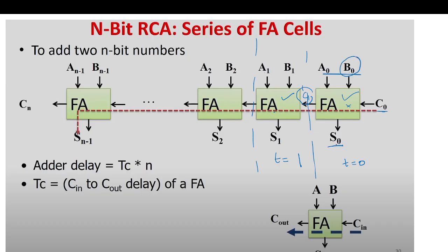So this data we wanted to come serially, like B0, after one cycle B1, after one cycle B2. So we needed two shift registers for this, and we needed this output to come here so that we have this feedback and it will perform. So in this way only we were making the ripple carry adder.